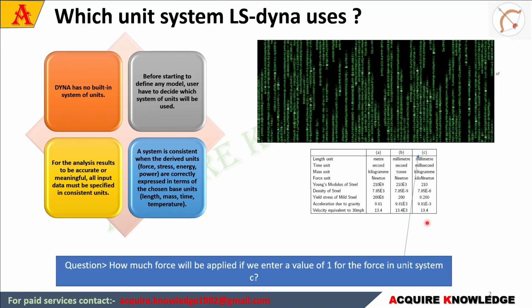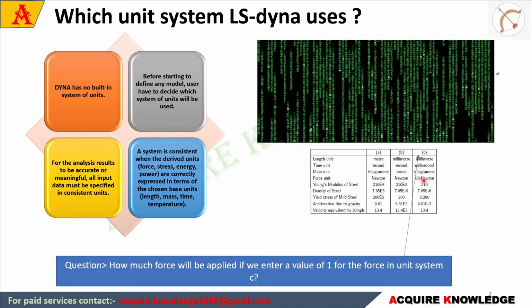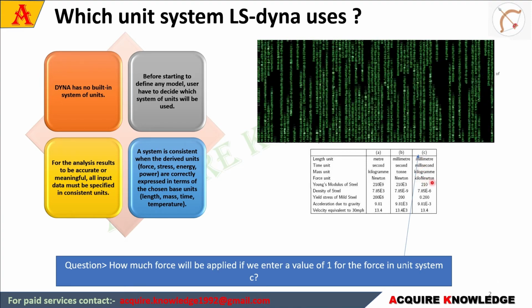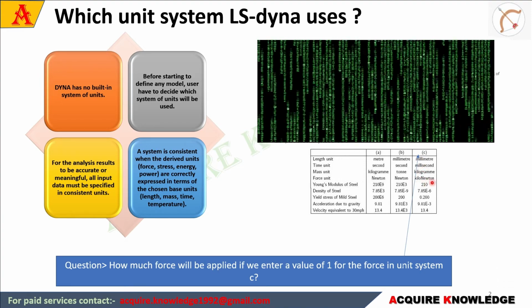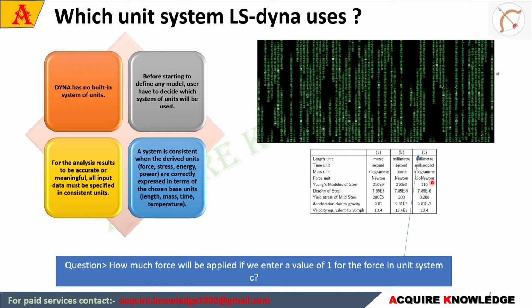Okay, so the answer is that if we enter a value of 1, based upon the force unit, which we can see from the base dimensions, it will be kilonewton. So the solver will interpret or apply the values in a physical sense. Like, in the physical sense, on the simulation model, you are applying 1 kilonewton of force.